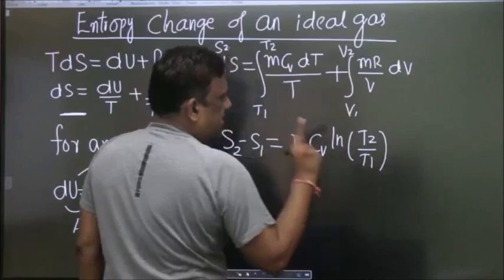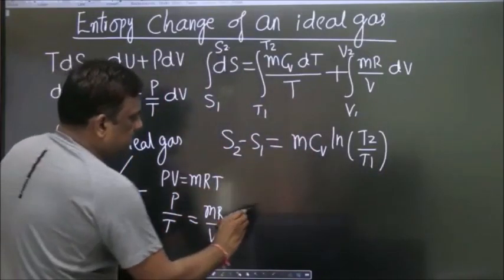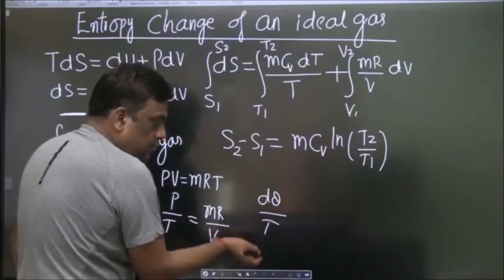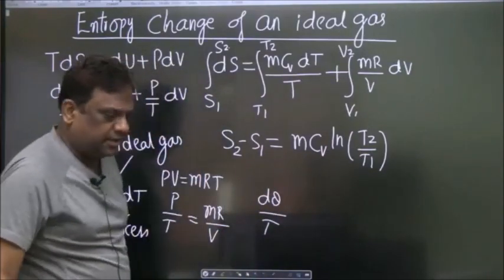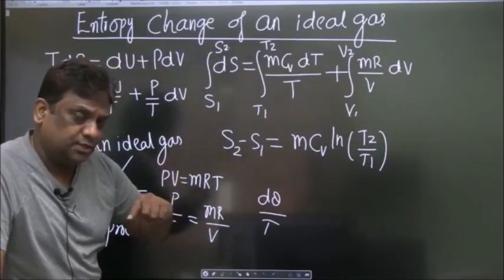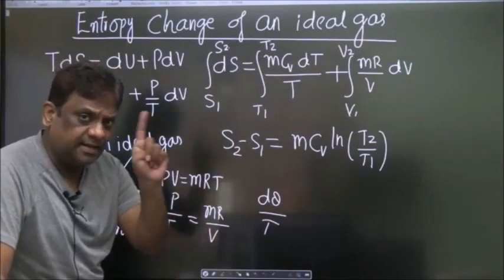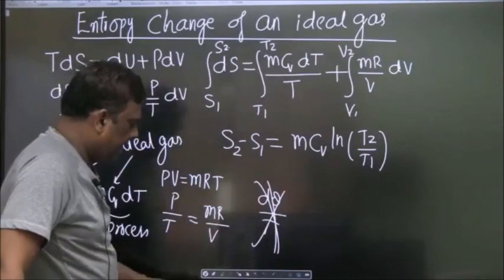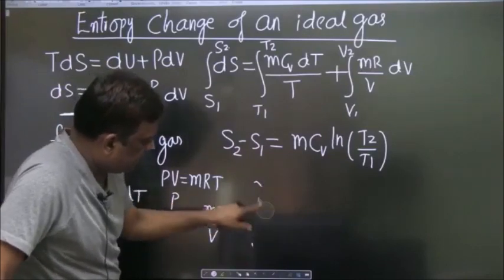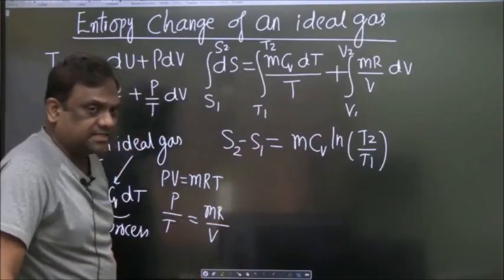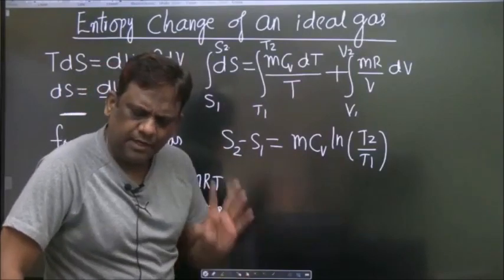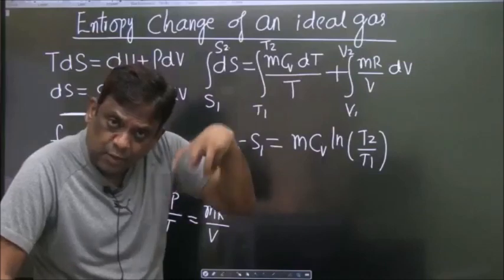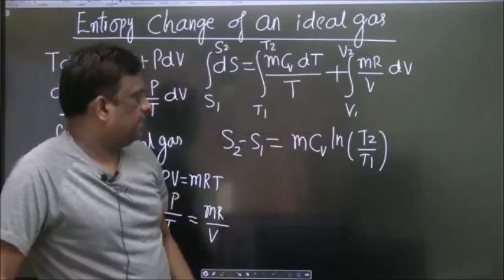And in all these entropy problems, please listen. We started with Q by T. So always remember, in entropy, Q1 by T1 is equal to Q2 by T2. We started from there, and their temperatures are in Kelvin. So in entropy, temperatures must be taken strictly in Kelvin, even if he is not asking. Any working fluid, you should take it in Kelvin. The reason is we started with Q by T, and that T is in Kelvin. So you should be very, very careful.